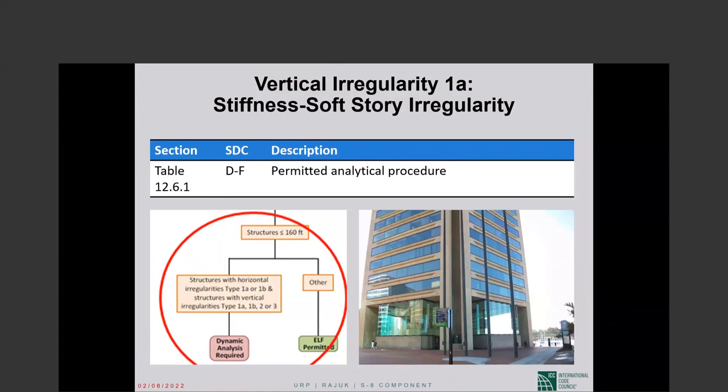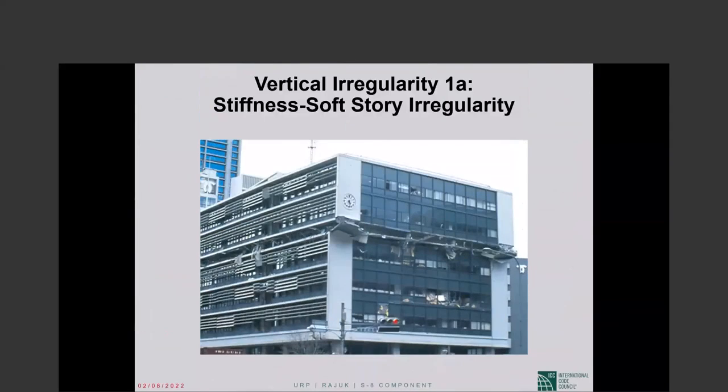Yeah. And in Kobe, I can tell you that this was almost uncanny. If you could tell yourself, I want to find a soft story, you will find it. You go around the block, you will find a soft story at the third story level. You go around another block, you will find it at the fifth story level. They were all over, like so many.